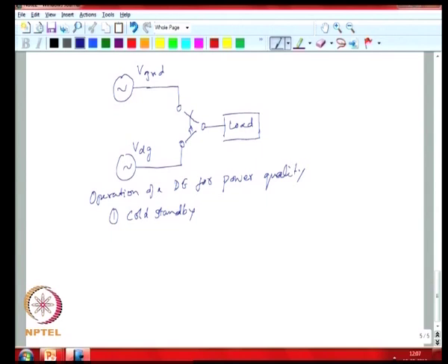So, one possibility is in response to the grid power quality being poor, you then start up a genset, then the duration of outage seen by the load would be longer, of the order of 20 seconds to a minute, depending on what is your startup time. Another way of running it would be a hot standby.